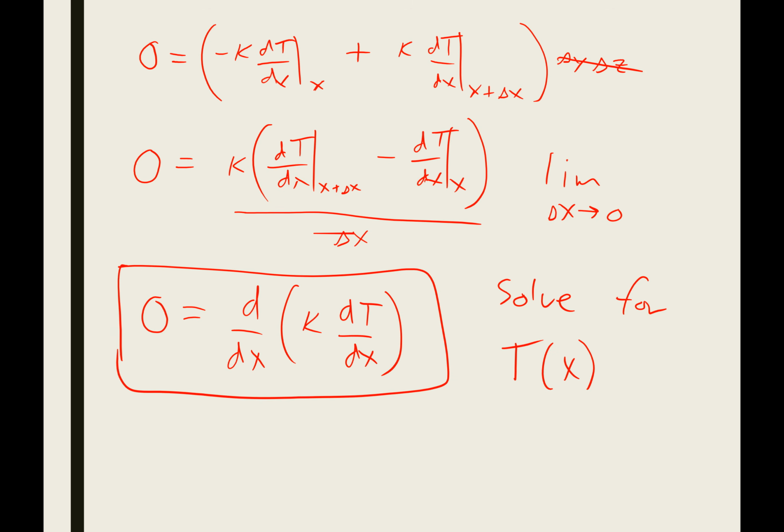Okay, so remember that functional form of this equation. Remember how that guy looks. It's fairly simple. So this is actually a form of the heat equation. We just derived the heat equation again, only this time for a very specific case, which would be a plane wall system. So we neglect temperature variation in the x and y direction. Steady state, so we neglect our accumulation term, and no generation, so we neglect the generation term. There's another way of doing this, which would be how you'll want to solve a lot of your homework problems.